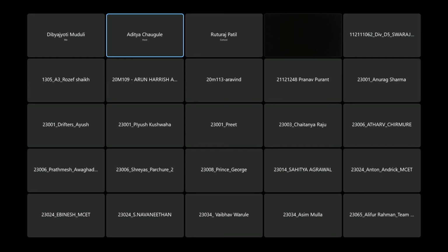You must have a target weight which you have defined, so try to get as close to that as possible. Just make sure that you don't add any redundant masses. One good resource to check that would be the info tab in the vehicle data set.